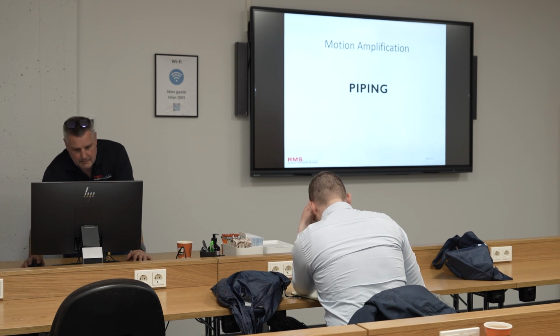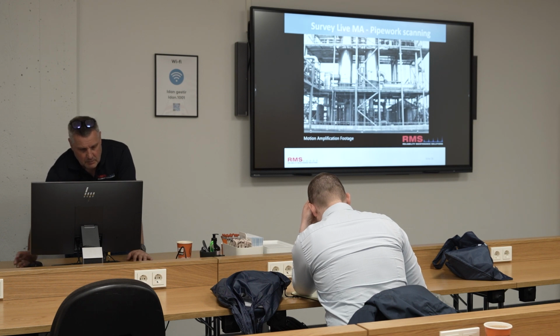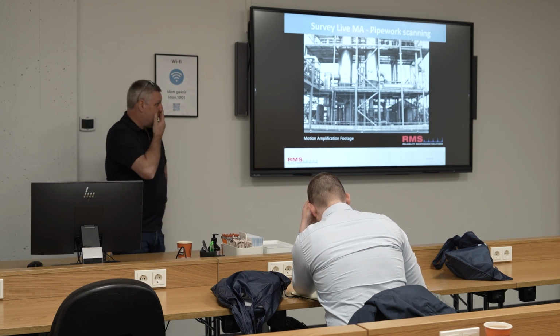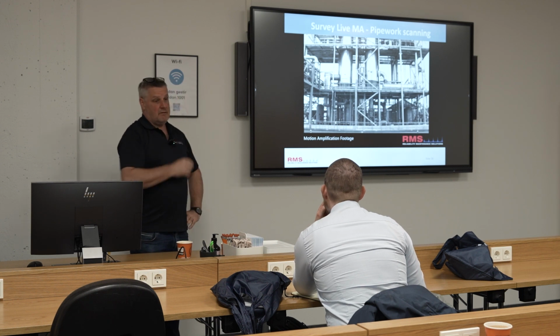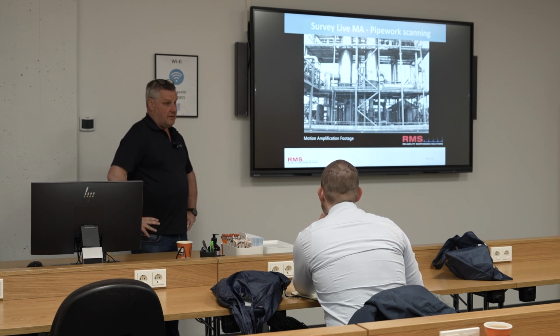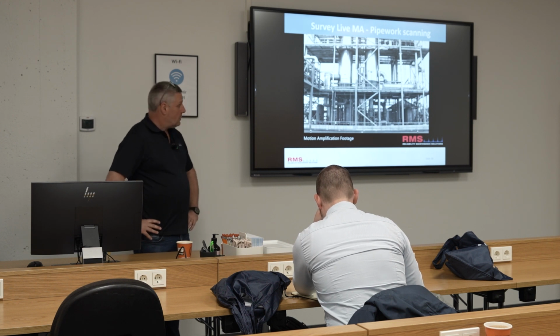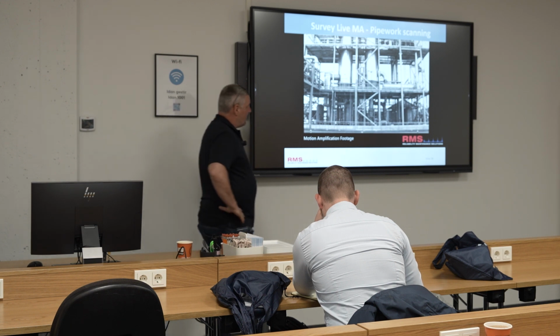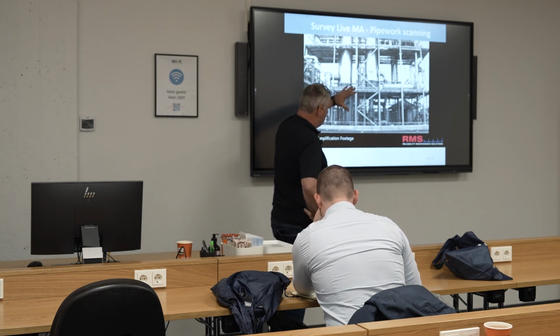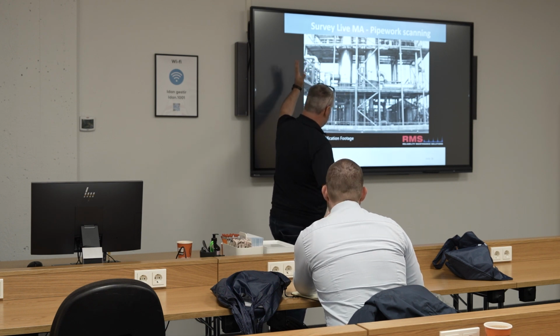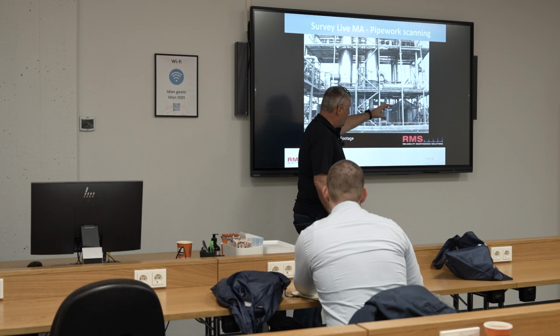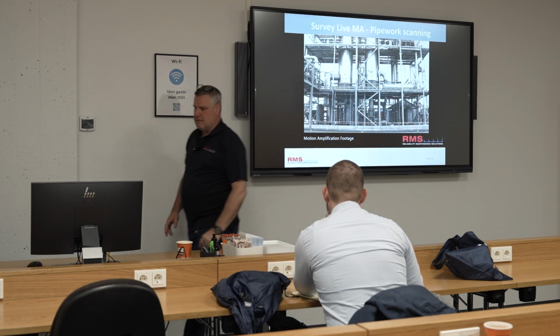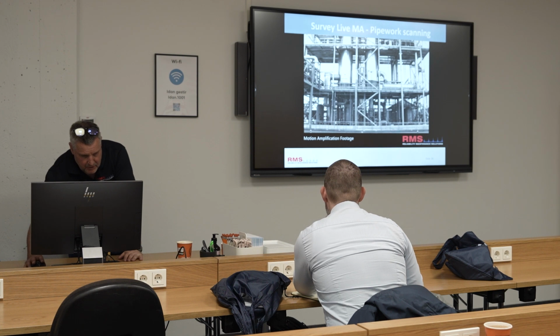Piping. We use it a lot for piping scenarios. I think I spoke to the lads earlier about Energy Institute guidelines. That's our vibration tolerance, really, for measurement, small bore pipe work. It's recognised all over the world as well. So rather than look at certain scenarios of pipe work, you can do a big field of view like that, and you can measure certain pipe works and get a nice view of the pipe work, and then zoom into the area that you want to after. It's really good for looking at pipe work and piping vibrations.